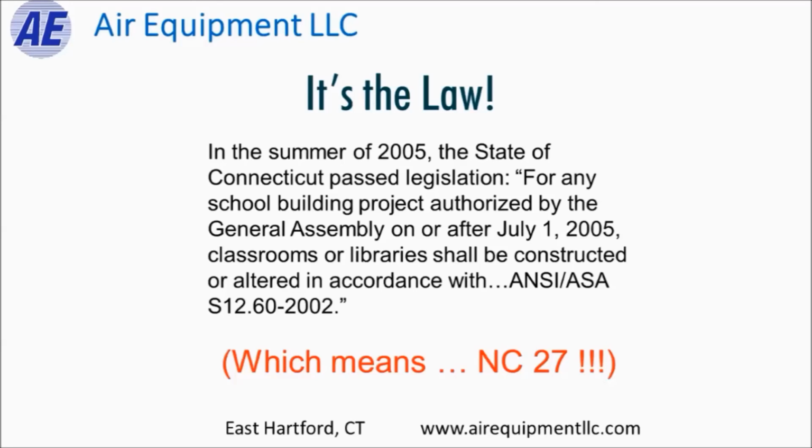Back in 2005, the state of Connecticut adopted legislation which says that for any school building project authorized by the General Assembly on or after July 1st, 2005, which basically is all of them, classrooms or libraries shall be constructed or altered in accordance with the ANSI ASA standard S12.60. So in other words, our new design standard for classrooms is NC 27. This is very stringent. Any kind of device that has a spinning impeller in it, like a VAV box or a unit ventilator, now most likely cannot be installed in or near the classroom.